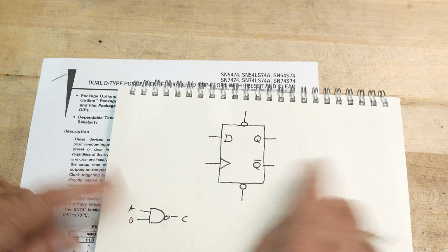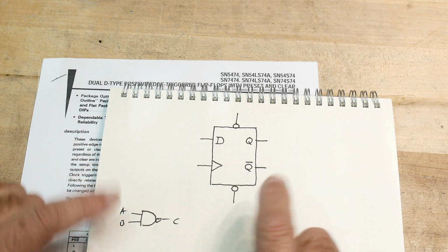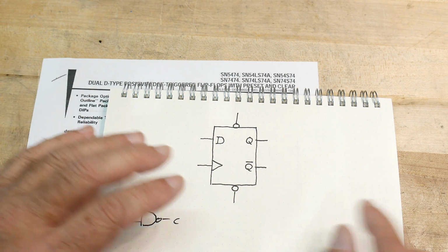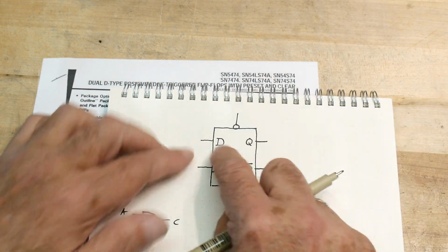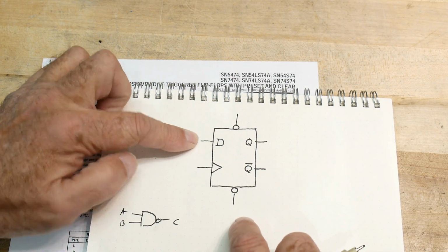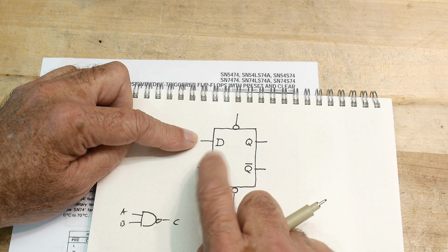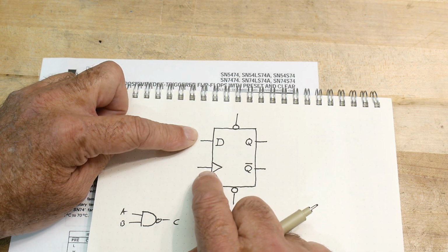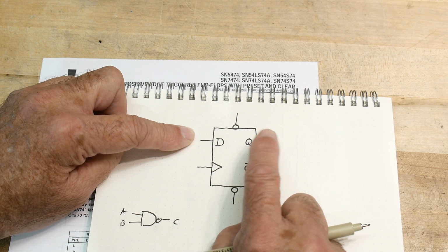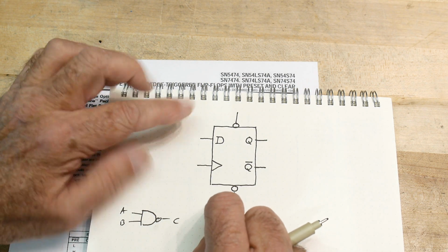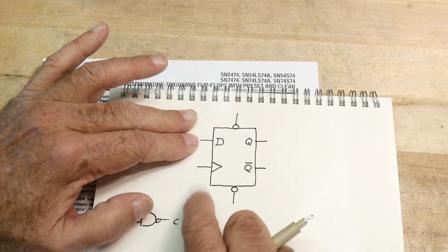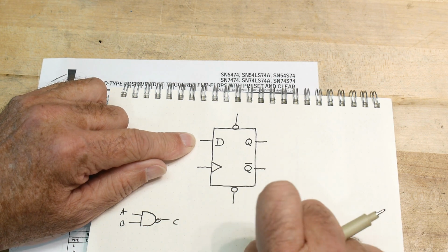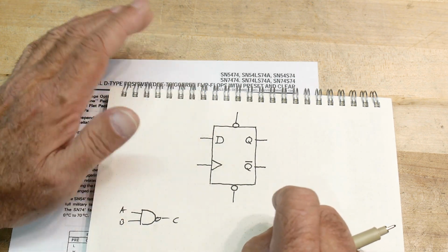But when you see this little chevron here, it says this is no longer a logic state device, it's an edge trigger device. What it does is whatever value D has, if D is 0, then on the next rising edge of clock, Q will be 0. And if D is 1, the next rising clock will make Q 1. It's like a sample and hold. It doesn't matter what's going on here until you see the rising edge, and then it'll sample that state and lock it in here. And not Q is just the inverse of that.